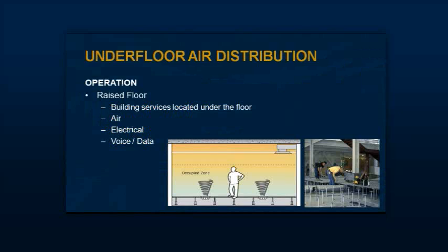So I look at this space and this space, and the traditional school approach would be to mix this void, but there is absolutely no need to do so. And if I cut this down by using stratified systems, I drop my air volume drastically. And I get people in close proximity that are very comfortable here.